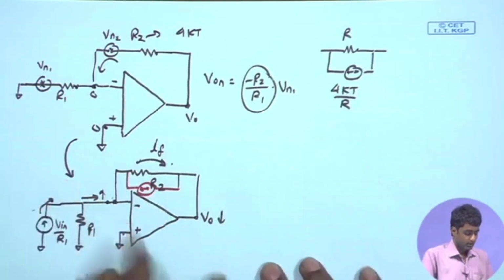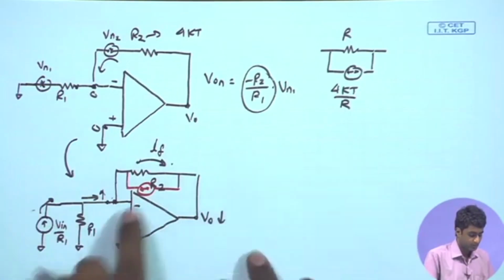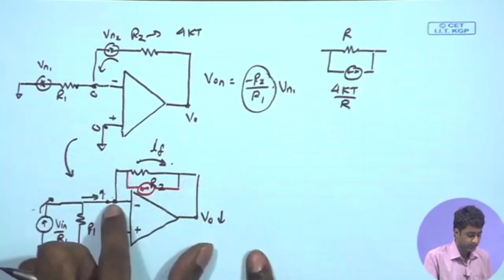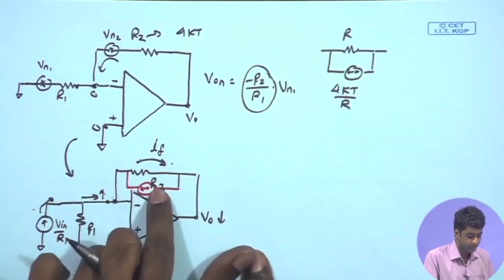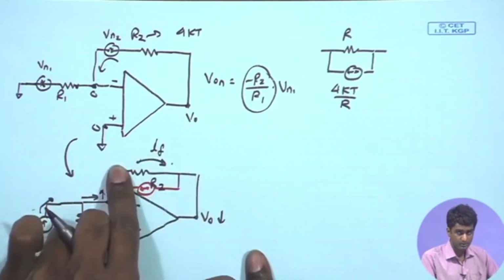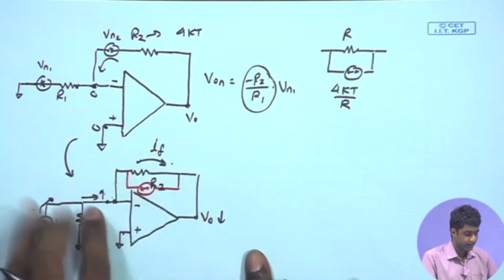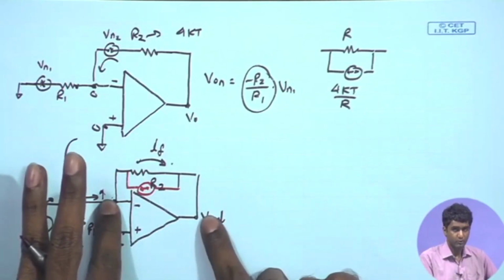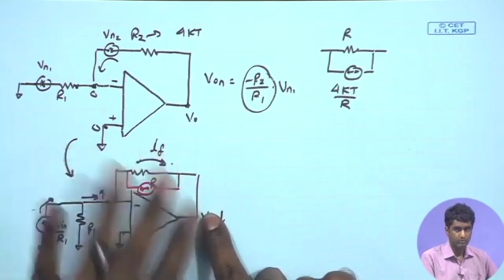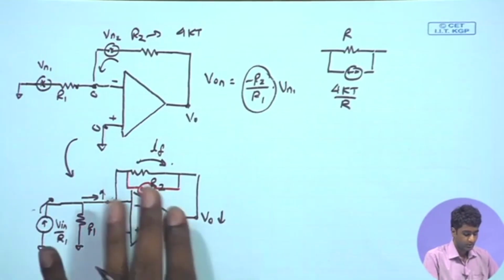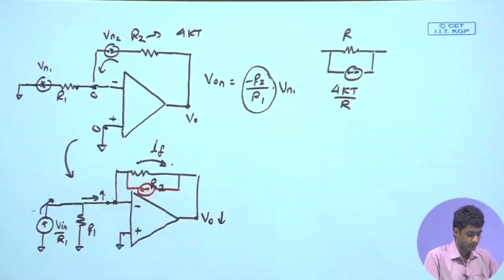As a result, what we can conclude from here is that because of the current mixing topology, current feedback terminal over here, a large choice of R2 does not corrupt the feedback signal coming from the actual capacitive feedback, and therefore, it is not going to significantly corrupt my output signal on the overall closed loop feedback operation. So, now let us see what is the role of this R2 in frequency response.